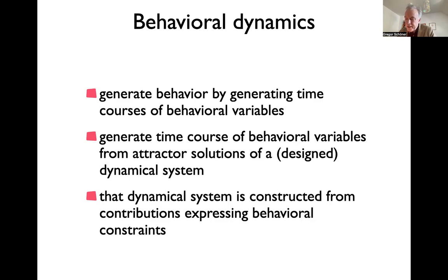And you'll see that it plays the role that the system will be able to deal with time varying sensory information about targets. For instance, if the target were to shift as you're moving, this stability would automatically take care of the robot compensating for that shift and catching up with the target, tracking the target. Or if there was some other influence like obstacle avoidance, and that pushes the system away from the target, when that obstacle avoidance goes away, the system will be able to recover the desired solution.